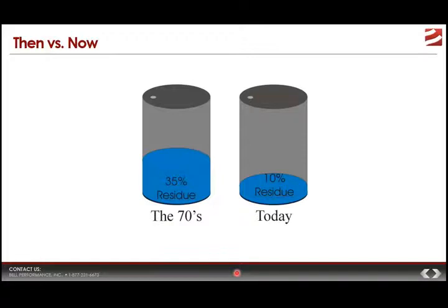I believe the most current data shows that they can get 93% distillate and leaving only 7% residual. So we're only getting maybe 7% of the crude oil volume is residual product. This, of course, includes heavy fuel oil and heavy marine fuel. And so the fact that we're getting a lot less of the residual fuel than we used to, well, this impacts the characteristics and the properties of the marine fuel oil that we pull out of this residual.